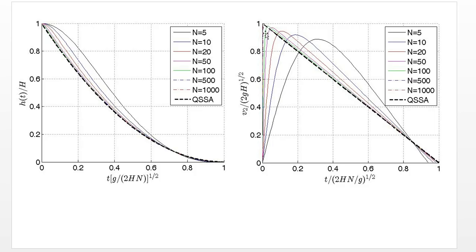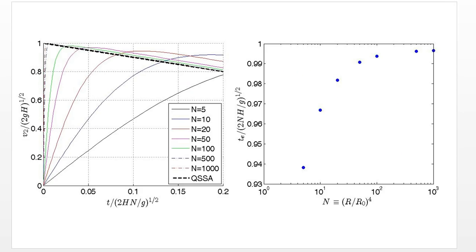And if all we want to do is compute how long it takes the tank to empty, this initial transient period is not of any concern. But let's zoom in on this region a little bit more and just see what's going on. So here we go. We can see for n equals 100, by time of about 0.02 in dimensionless units, we've almost attained exactly the quasi-steady state approximation. And if n is any bigger, meaning the hole is even smaller, this initial transient is very, very small.